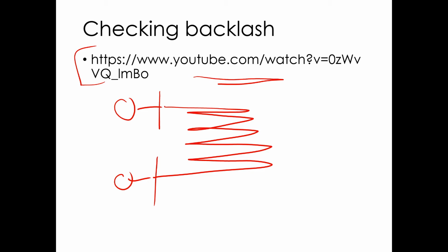Because backlash is not cumulative. What's going to happen is it's going to feed this way, and then there's going to be this dead period where I move the input, but the output doesn't move, and so when I come back, I'm going to end up just a little bit short. That's the backlash. Now what happens when I try to feed this thing back the other direction is I'm going to